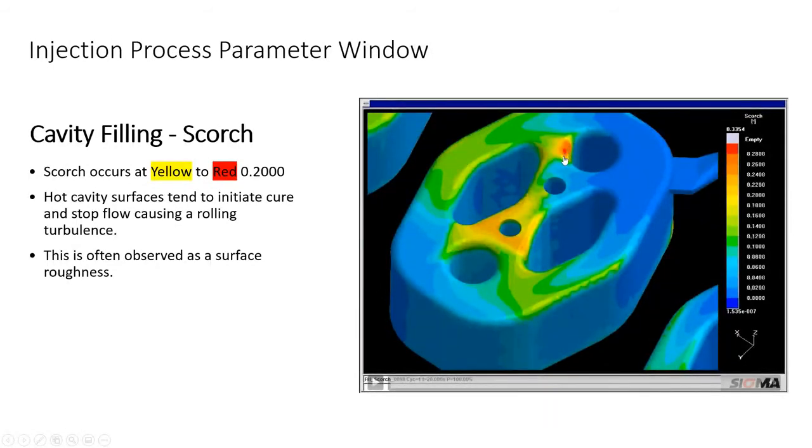And what does scorch equal? It means poor elastic properties. The physical properties aren't going to be very strong here. This is obviously a type of connector, so this is going to be a high wear point. It's a place where perhaps a seal will be broken, and this part should be defective based on what we see here.